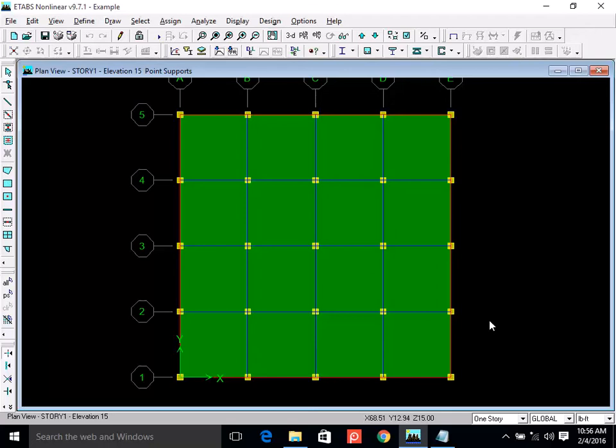Can you quickly do the math? 170 divided by 6, what do you get? 28, say 30. So right now, based on our sitting arrangement, in every 1 square foot we have a load of around 30 pounds per square foot.